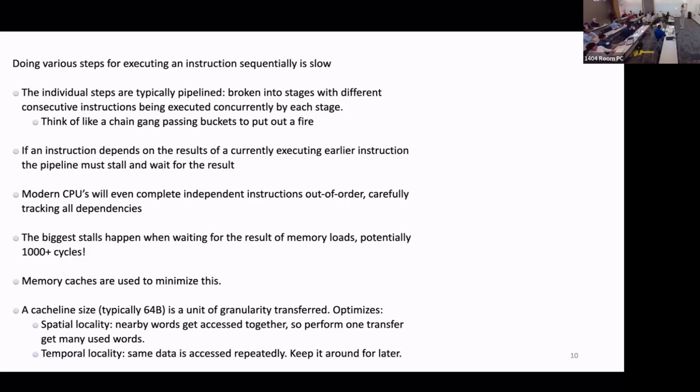You retain on-chip copies of data, and you have to remember whether it is modified and whether it has to be written back. They have protocols, MESI, they call it: modified, exclusively owned, shared, or invalid, to handle which core owns which line of data, and to make sure it executes the same way as if there wasn't a cache in the first place.